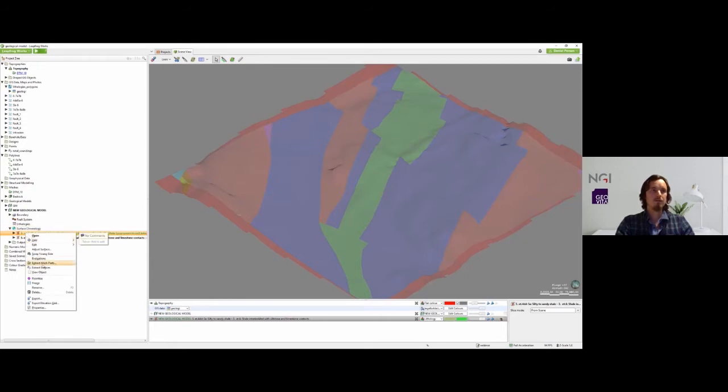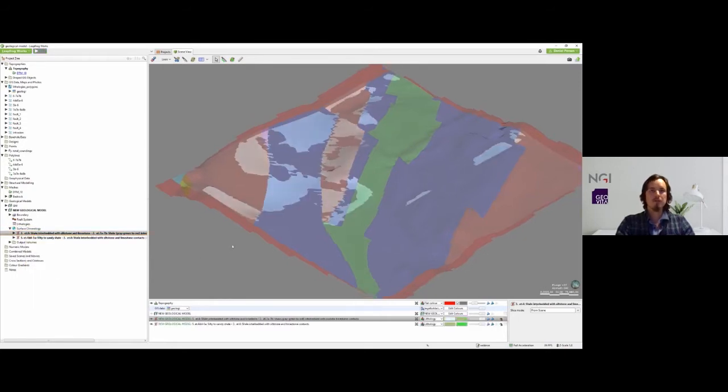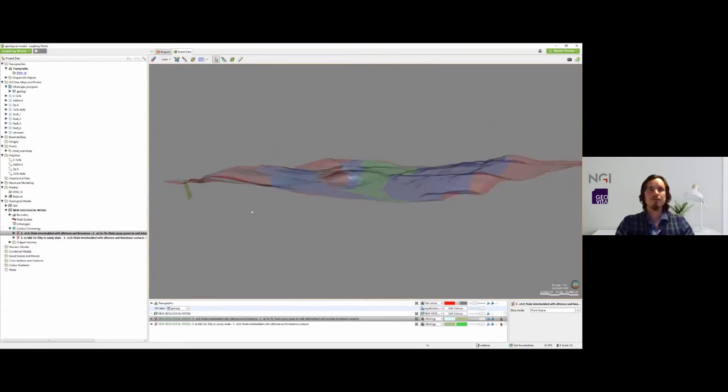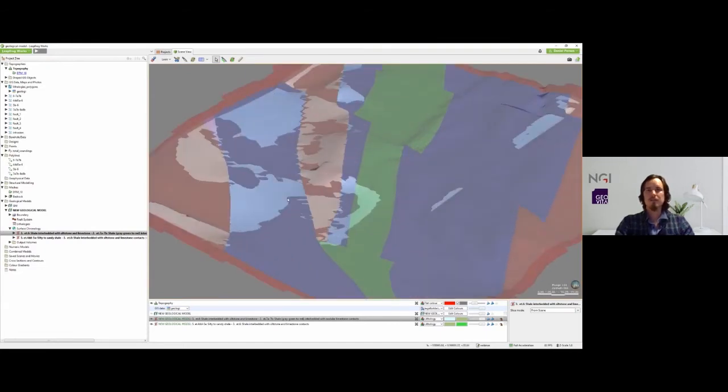And then you can view this one also. And here you can see that the surface is just flat. It doesn't have any structural data to it. So it obviously needs to be edited. And I will add a polyline to this surface to edit it.